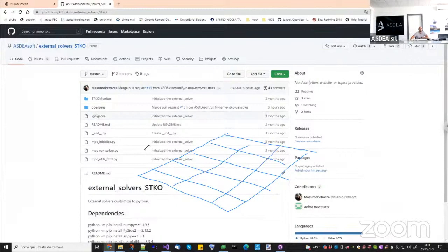And then you have a point here, which represents your train, for example, where basically you have a vertical force, which is the weight of the train. You have a mass, and possibly you have a damping and the stiffness of the train as well. So what we want to do is to create an automation for creating a node, creating the projection of this node onto this plane here, and creating a spring and a dashpot here. So an entire system that has a load, a mass, a stiffness, a spring.